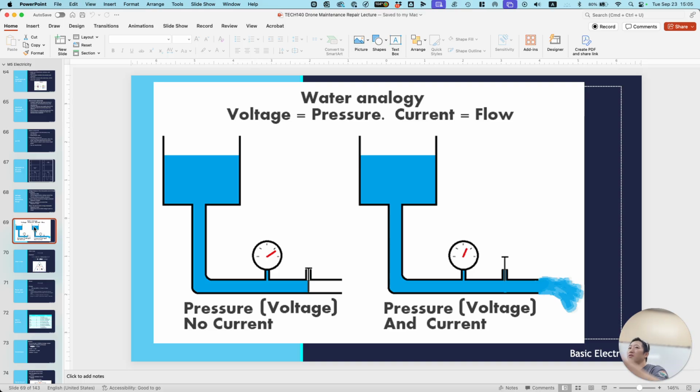Like if you just have a normal AA battery, right? Those things are 1.5 volts each. That's what it's supposed to be. Does anyone have a AA battery? Okay. Usually if it's fresh, they might start off at like 1.6 volts. But over time, just from experience, does anyone measure their battery to know if it's dead or not?